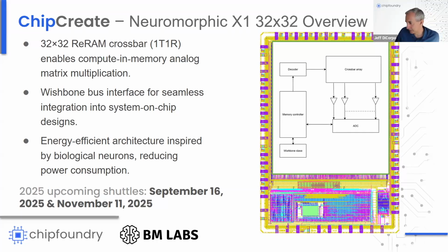Okay, so I think that maybe explains it. Hopefully that clarifies the mode and how you operate. When you're writing, you have a mode set when you're filling the FIFO with the addresses and data. When you're reading, you have a different mode for reading back. You're just filling the addresses, but then you're going to come back later and read off the FIFO to get the data back. Correct. So the user has the full flexibility when writing the wishbone data command. He can specify the first 2 bits, whatever he wants to do with the device, the column and row address, followed by what data they want to send. Yep. Makes sense.